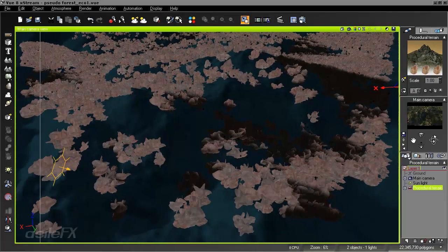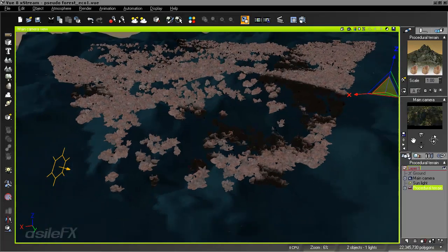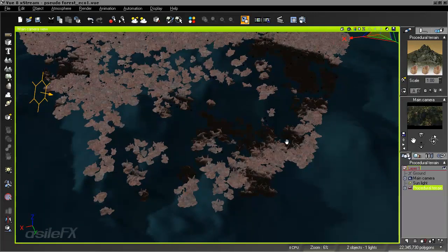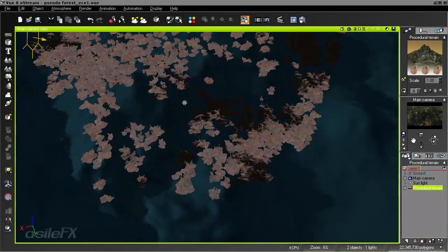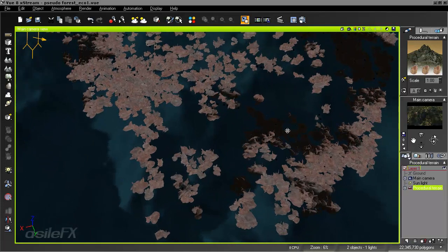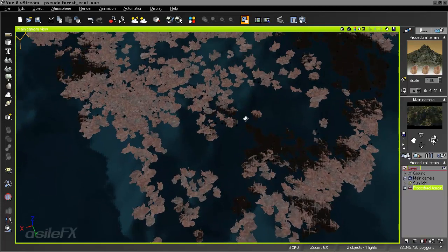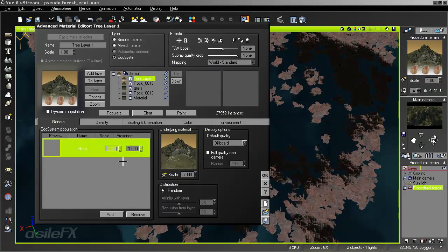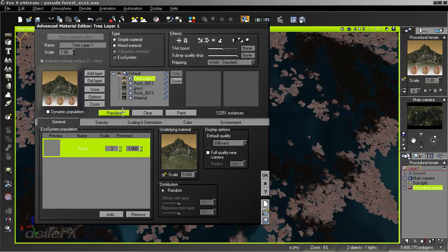I'm going to go ahead and duplicate the camera and just move out a little, and then position the camera looking downward more, and that way we can reduce the amount of objects we have, and I do want to end up decreasing the scale a little bit further. So we're going to go to Scale, set it to 3, we can repopulate, and it should render correctly with that density setting for the projection.